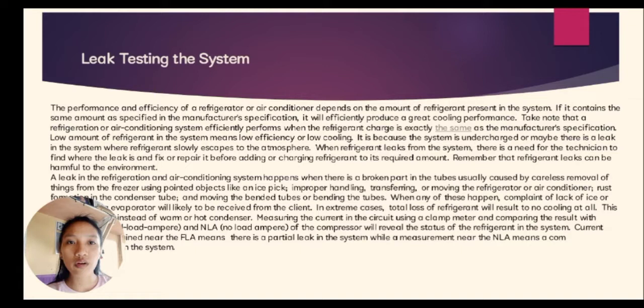A leak is a condition where refrigerant slowly escapes to the atmosphere. When refrigerant leaks from the system, there is a need for the technician to find where the leak is and fix or repair it before adding or charging refrigerant to the required amount. Remember that refrigerant leaks can be harmful to the environment.